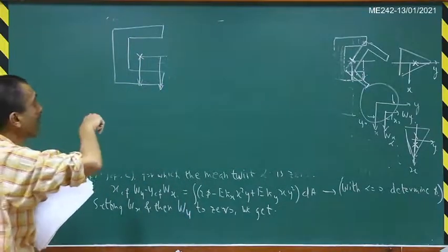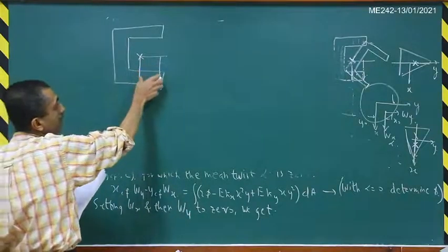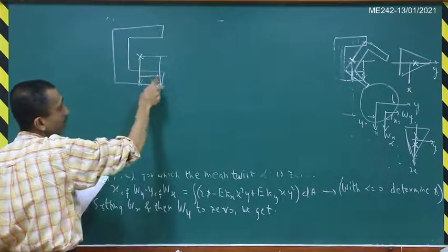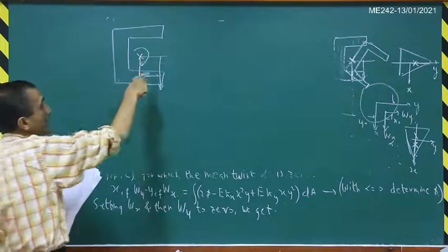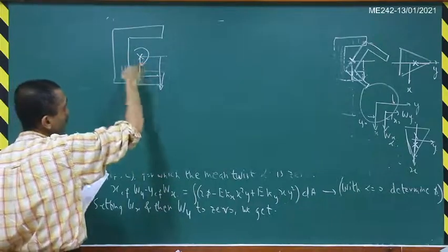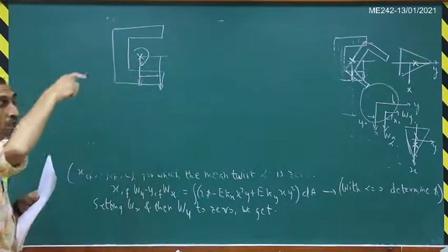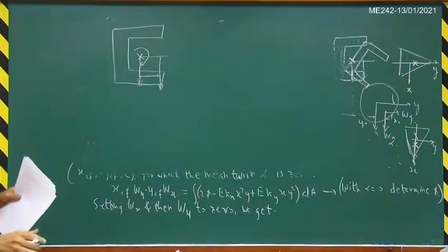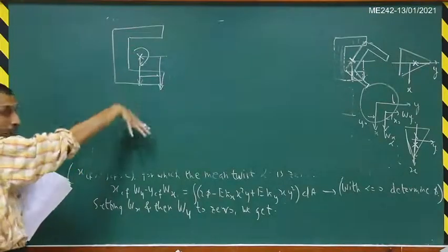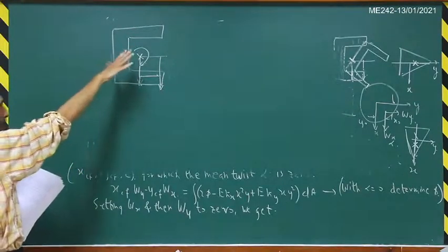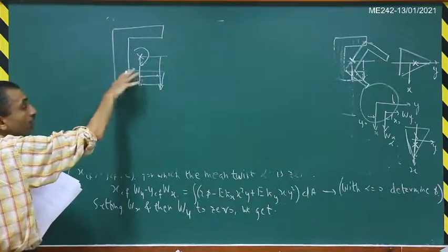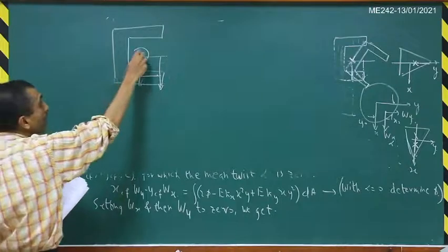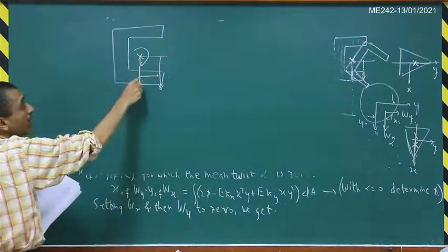One part is a torque, which is this distance times this load. Plus, you can shift this load here and then apply this particular moment. So you can split this problem into a problem of bending with no twisting, not exactly pure bending, meaning the load is passing through the shear center, plus a torque.